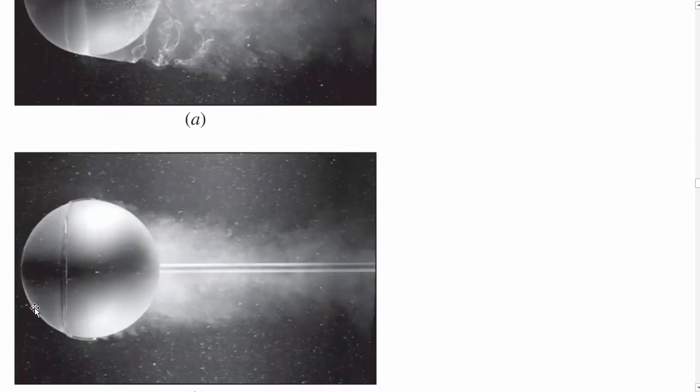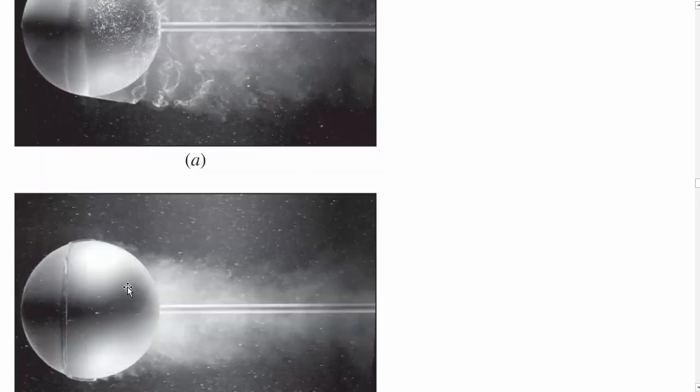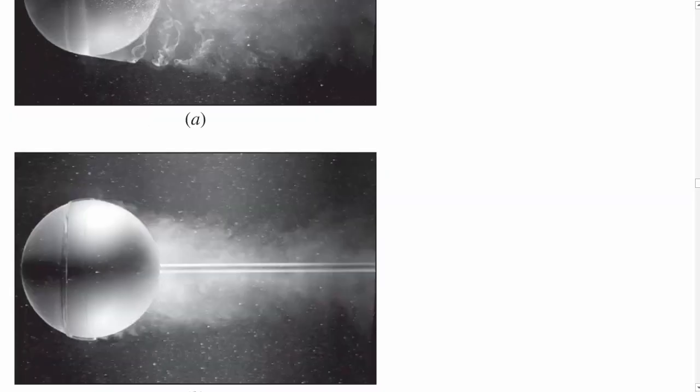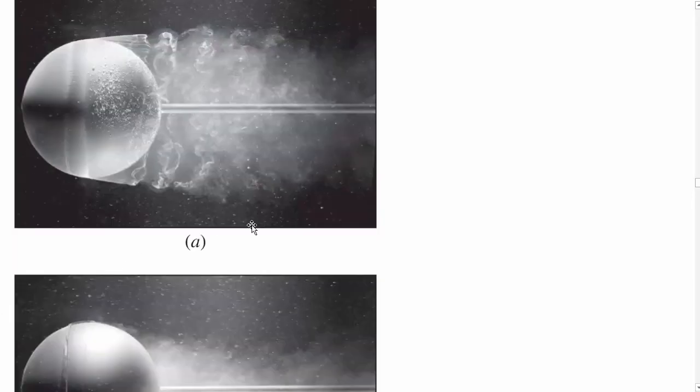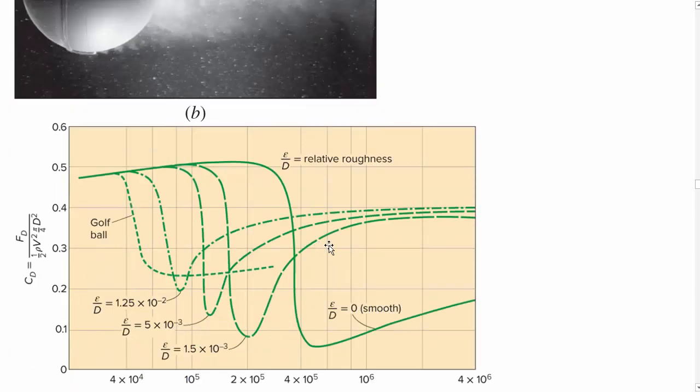Yes, this friction drag is higher on this thing, but friction is so much smaller of a fraction of the drag at these Reynolds numbers for this kind of a body, not a flat plate like we had in the last section. Even though the friction drag is higher, because the form drag is lower because of the smaller wake region, it actually can make a difference.